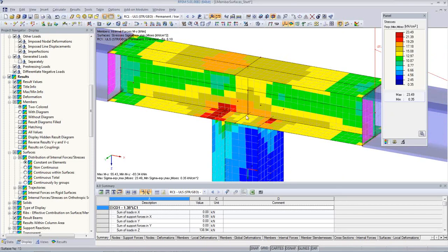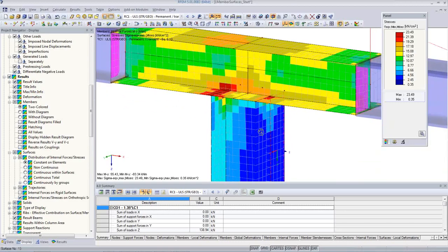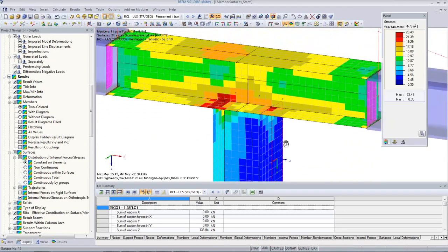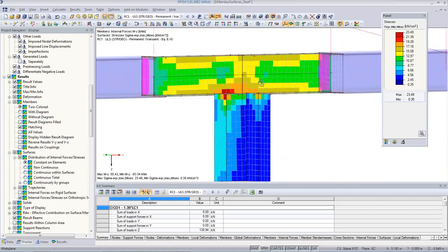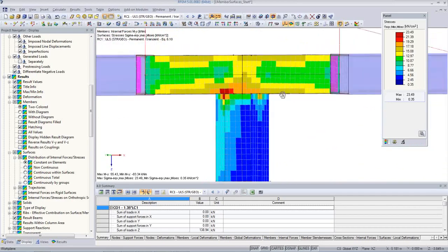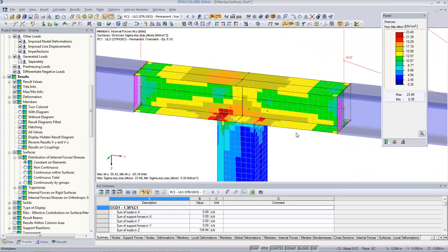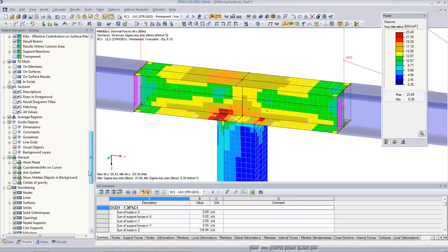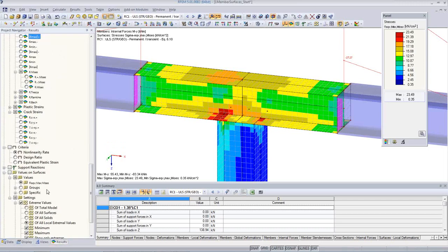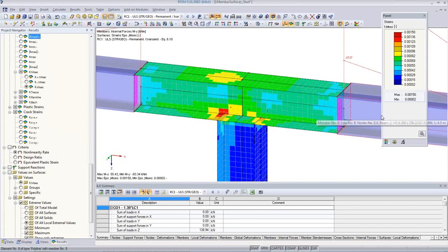We see here the red areas where we have actually the stress. It's a slightly bigger area than we saw beforehand, where we thought there was an extra overstress. This is due to the redistribution of the forces, because we now have also a different stiffness through the plastification. Also, I can take a look at not only the stresses, but also the strains, because I have to make sure that I do not have endless strain in the material.